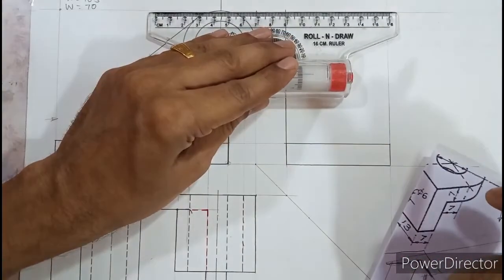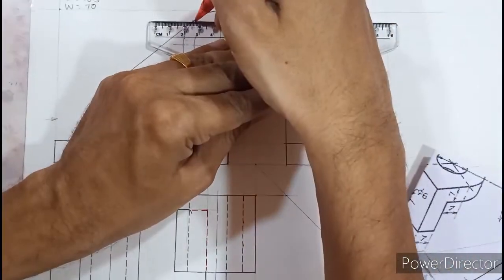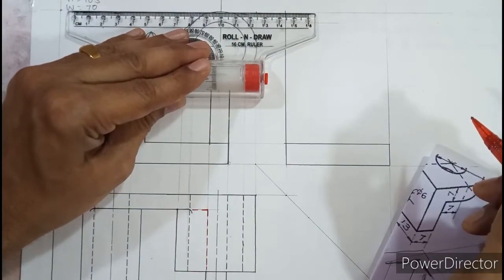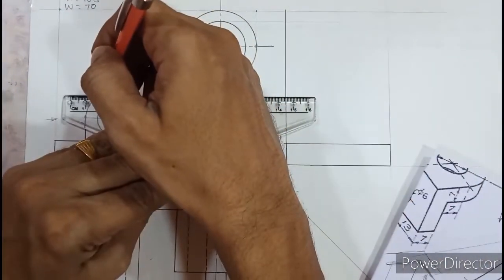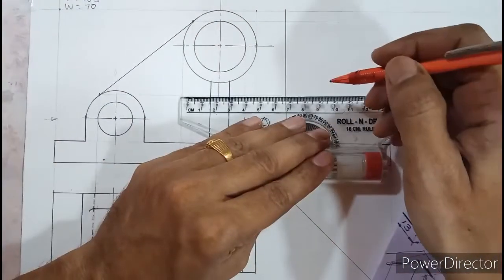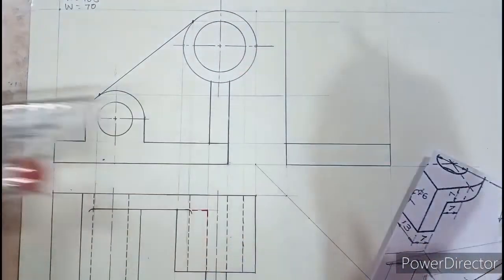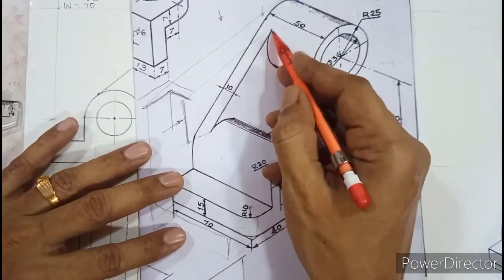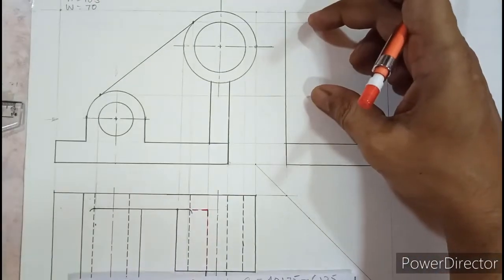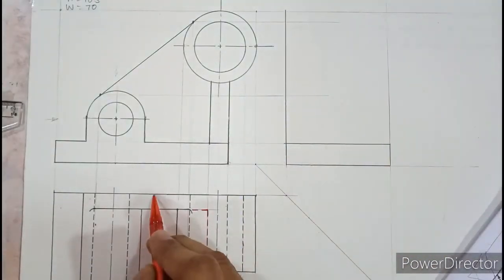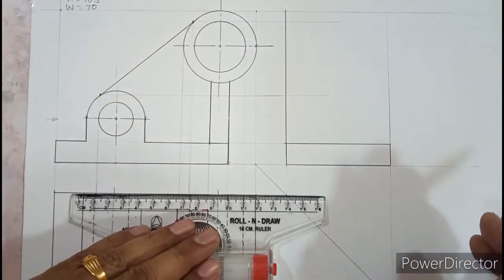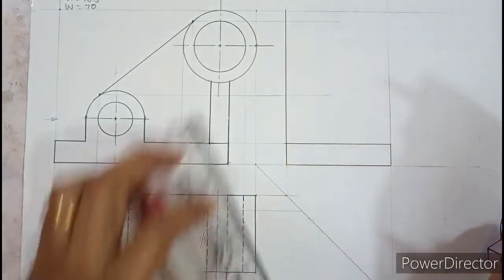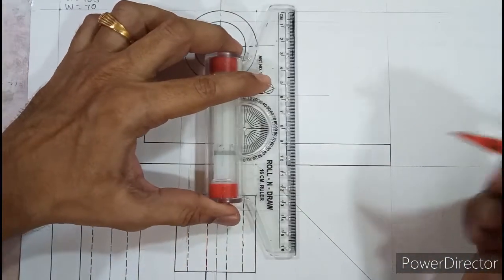So from here, if I start with, I will extend this down, project here. Then from here, we will roll and project the next merging point. So if you extend both the merging points a bit, so this is your height of the rib, that is the merging rib. So this merging edge of the rib is in between this, and the width is 10 millimeter. So that 10 millimeter I will extend from top view and I will transfer it to the side view.